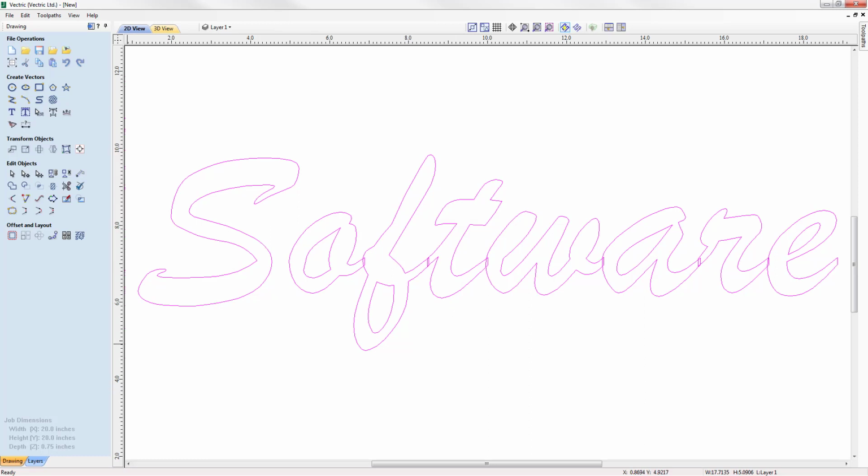Some toolpaths, such as the V10 toolpath, would require us to have one continuous vector to cut in between, which the V10 toolpath actually handles internally without us having to weld the text. And so it would create a toolpath as if it were one continuous vector. However, there are many times with script fonts where characters overlap, we may be left with a few inconsistencies.